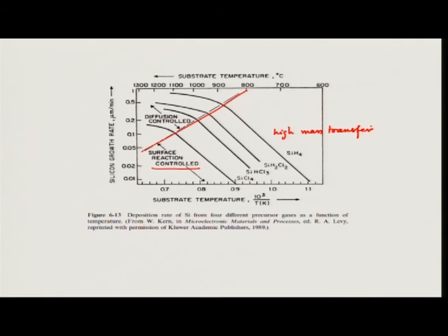If mass transfer rate is high, then it is controlled by surface reaction rate, and on the other side it is diffusion control, which means reaction rate is very high. So, these are two different regimes, and we can find a demarcation between them following the thermodynamics and kinetics of your reactor or by some experimentations.